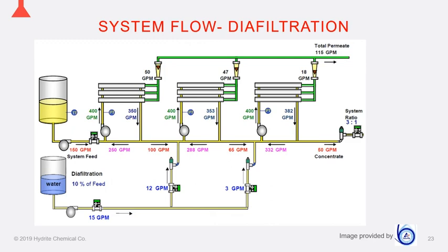So it's going to get sucked into the pump. Now it's got an additional flow, and you can see how that changes the numbers a little bit with regards to the permeation rate, because now we've got more water through there. So our osmotic pressure dropped a little bit, which allows a bit more flow. And it changes a little bit the dynamics of the recirculation coming back through.